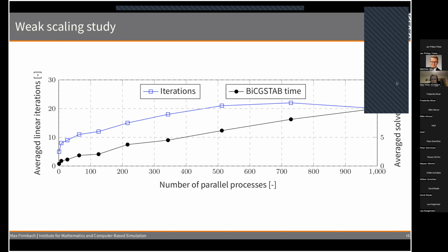Looking at the average solver time, this is of course not optimal. I'm using a BiCGStab method here because I ran into some memory problems at some point. Of course, our system is for now symmetric, but anyway, we can see an increased solver time for each problem, which is not optimal. I would have liked to see a more flattened out graph. But for the beginning, we are fine with that, and we are investigating the behavior a little bit further, especially this very linear behavior overall.